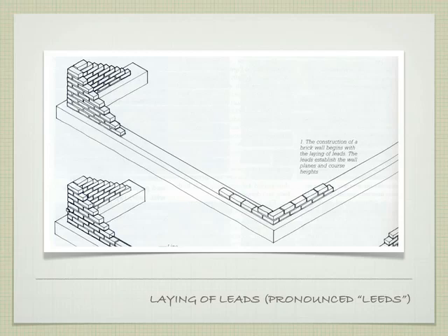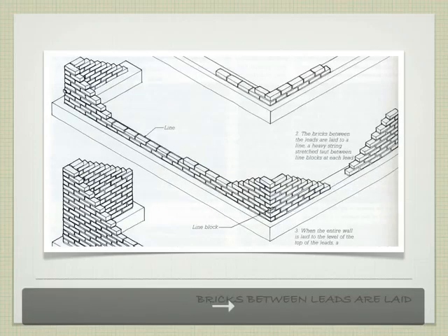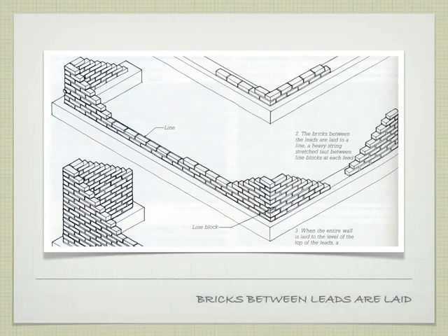So if we were actually going to build a brick building, right, what we would do is we'd first start out by laying what are called leads, right? And these are basically the corners of a brick building, right? And they're the establishment that's going to take us through and actually allow us to build the building as a whole, right? So we start with that first row down here, and we'll go through this in much greater detail, right? That first course, right?